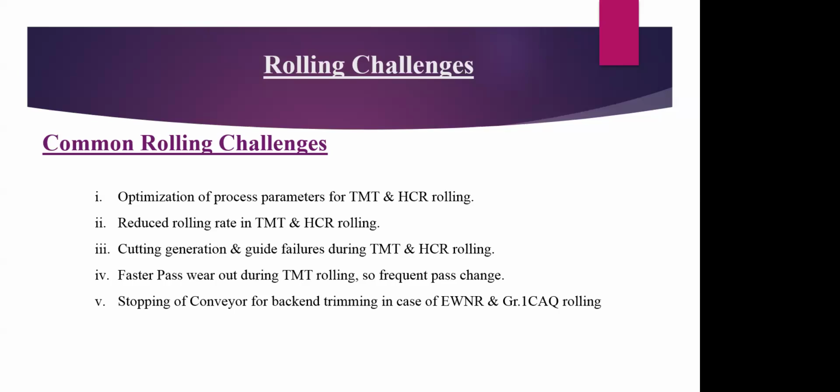So the advantage that we want to take with the help of HSS roll is not exactly achieved, because now it is installed in only 2 stands. In case of plain rolling, supposing if we take say our pass change or the scheduled pass change, maybe after 3 days. In the case of TMT rolling, it has to be done the very next day, that is after 1 day of rolling, because the pass wear out is very fast.